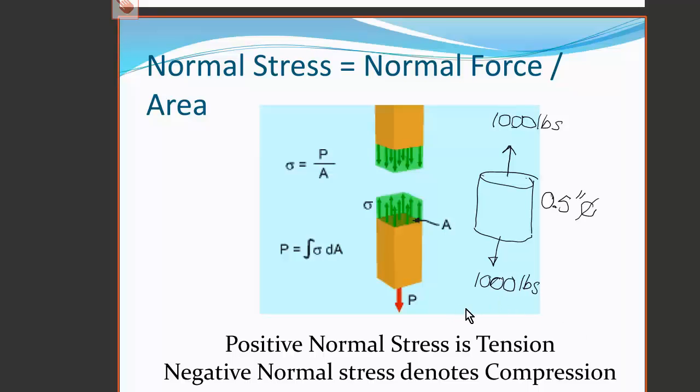The stress in this case will be the force P, which is 1,000, divided by the cross-sectional area, which is pi times 0.25 inches squared.